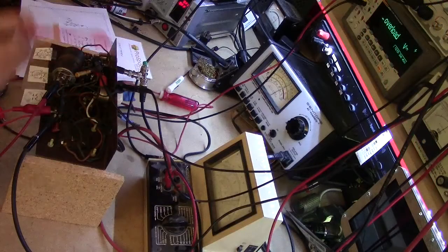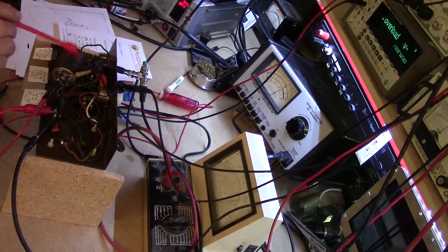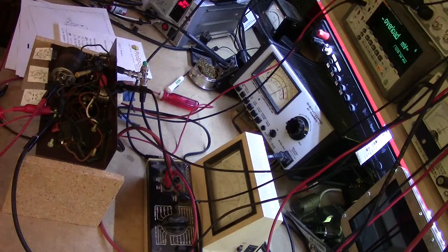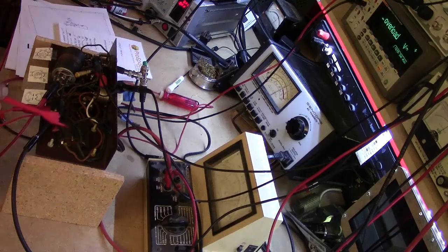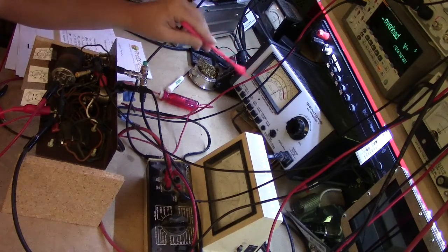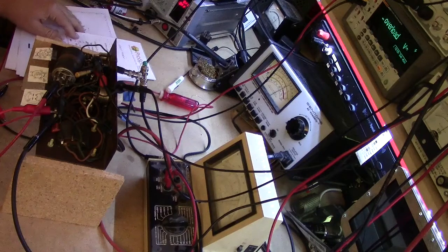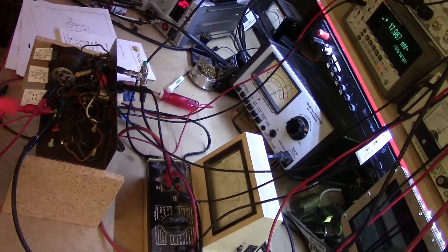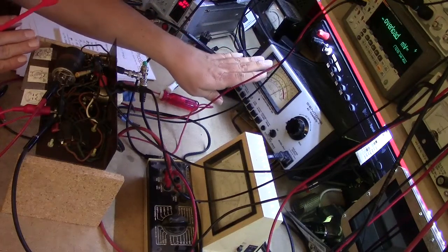All right, here's our test setup. We have the amplifier here. I don't have a rectifier tube in it, and I don't have the pentode power tube in here either, but I am using the power transformer for the filament voltage for my 6SJ7, which is over here. In order to get the filament voltage to be right, we're using the variac here, and I dialed my filament voltage in to be 6.3 volts. So that's running the heater in my 6SJ7.